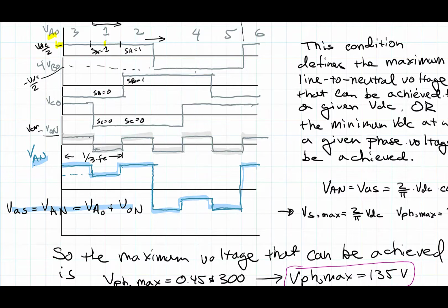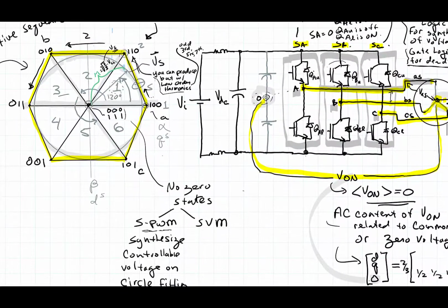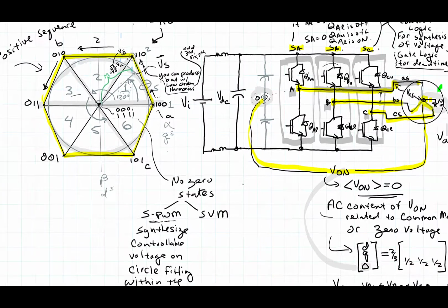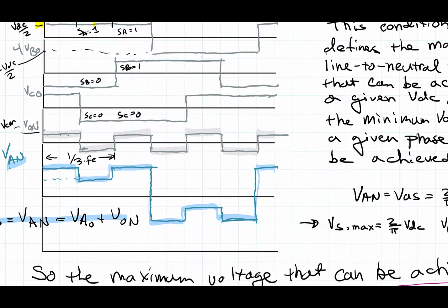So we have a very interesting thing. If my phasor vector, that is the phasor that's moving around, is moving around on this edge here, it's physically going to reflect onto the three phases looking like this shape. And this actually is a shape that, if we think about a Fourier series representation of the different frequencies involved, you've got a fundamental frequency, obviously. So that would be your FS1 or the FS. But you've also got a third harmonic involved here.